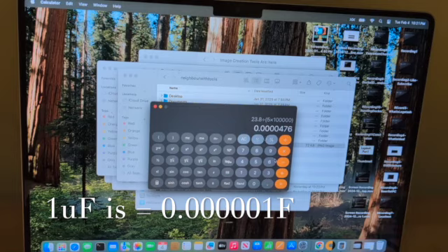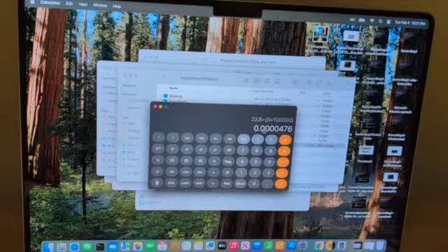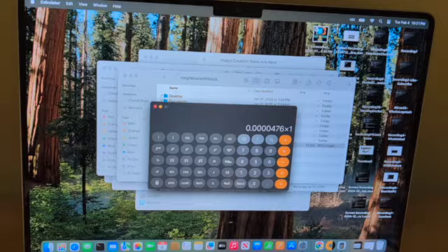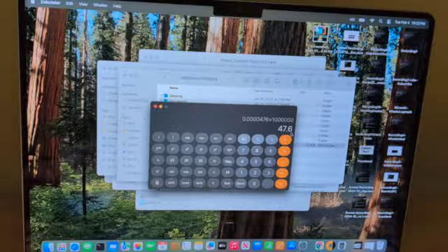Most of them, they don't write these on the components, right? Like they don't write 0.00. It's usually in the closest units, so that the number is convenient for you to see. So at this level, let's just times it by a million and call it a microfarad, okay. So according to our calculations, we have 47.6 microfarads. And let's take a look at the capacitor itself.